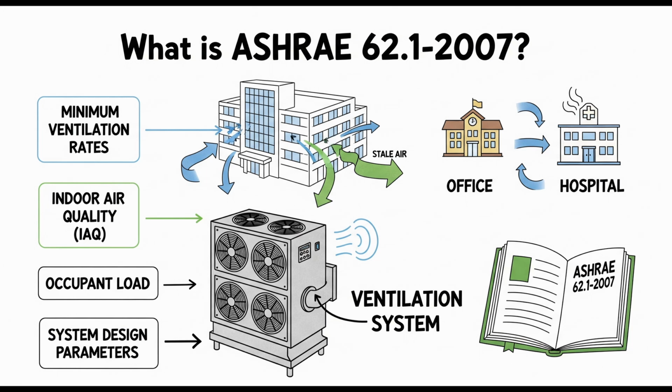It focuses entirely on containment and separation. You have to clearly designate the ETS areas. You must make sure the non-smoking areas are at a positive pressure compared to the smoking areas, meaning air always flows out of the clean zones towards the smoking zone, never the other way around. Like an airlock almost. Kind of. You need physical air barriers. You absolutely cannot recirculate or transfer air from the ETS area to any ETS-free area.